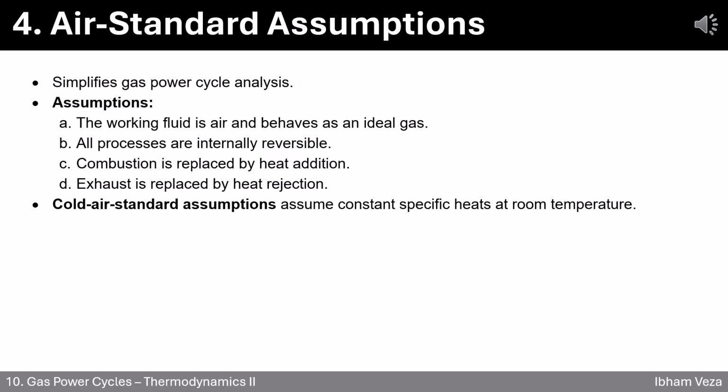Finally, there's an even simpler version called the cold air standard assumption. It treats air's specific heat as constant at room temperature, which avoids messy temperature-dependent calculations. With these assumptions, the math becomes cleaner and we can focus on the core performance, making it easier to understand and compare different engine cycles.